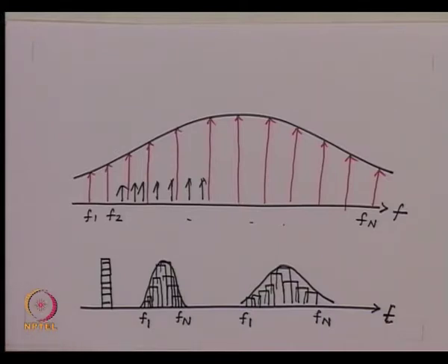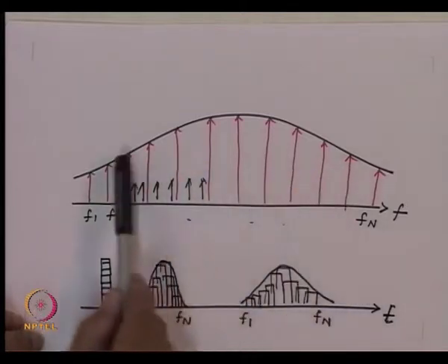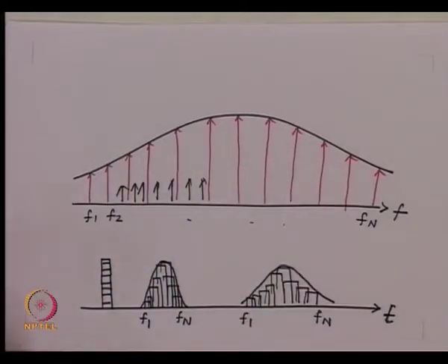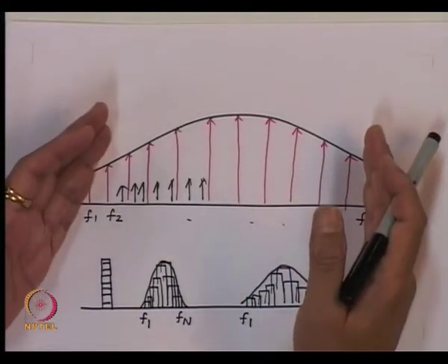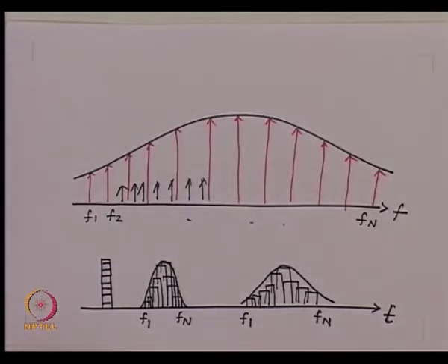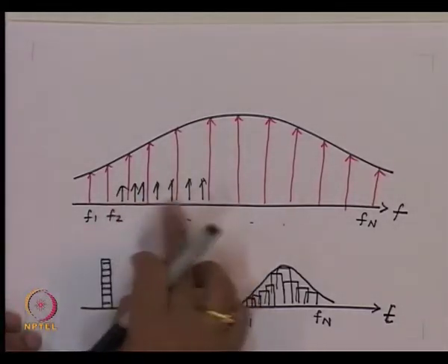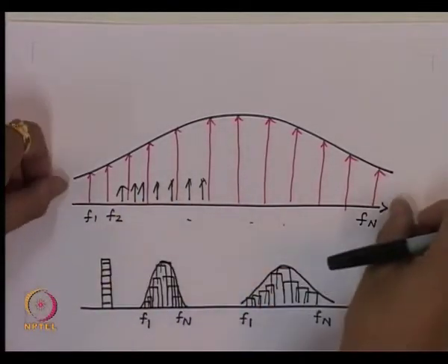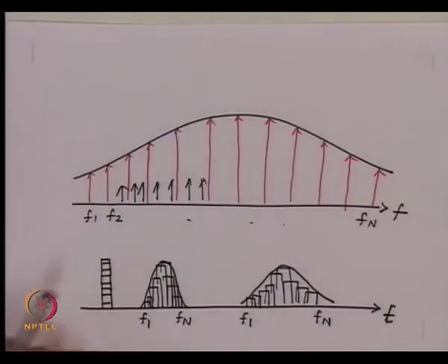What we find interesting in this case is that the spectral width required for optical communication is more or less the same as the spectral width of the source. Because even if you have sidebands after modulation, the spectral width is hardly going to change, only by a very small fraction.